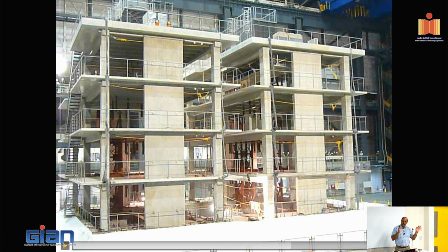So obviously both of them survived, right? Both buildings stood on the table. You could see that in the cast-in-place, you're starting to see the damage because of the plastification, whereas the rocking took place basically at the base of the wall. They designed this structure to be rocking with the walls going in this direction, but for the other direction, it was a frame structure, but still with the rocking concept.